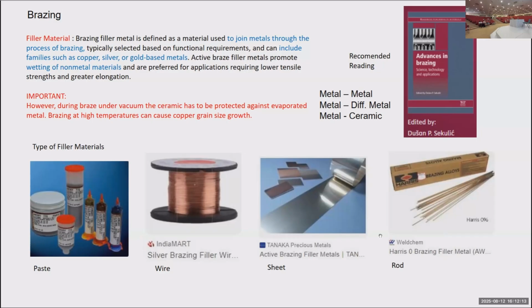Due to the oxidation, everything related with the oxides, mostly. So graphite type vacuum or some molybdenum type? The heating element, heating elements mostly tungsten. Because generally in industrial vacuum furnaces, it's about up to 2,000 degrees, and you have to use it. But the problem is not the heat. The problem is shielding, heat shielding.